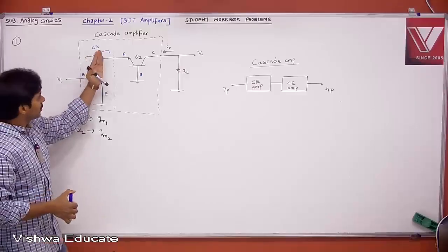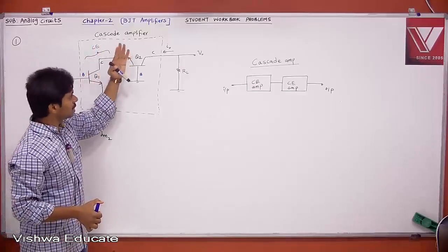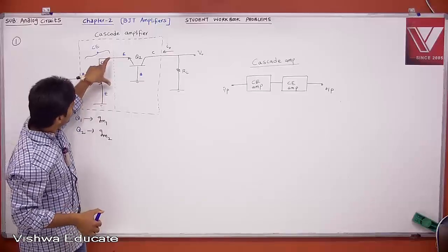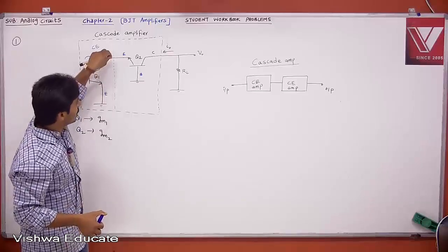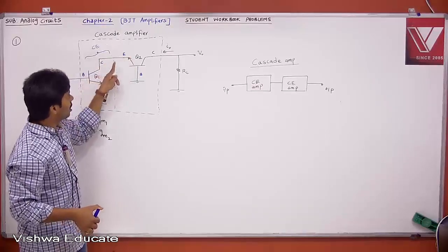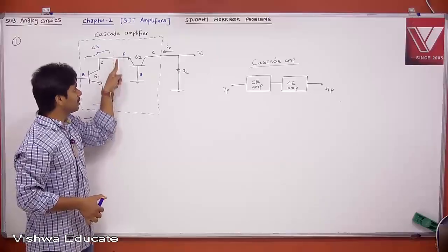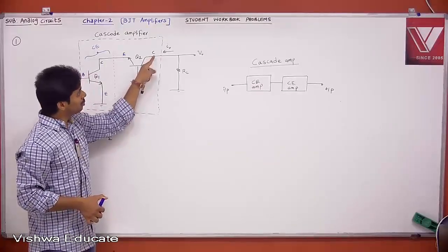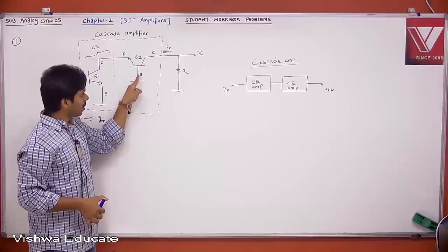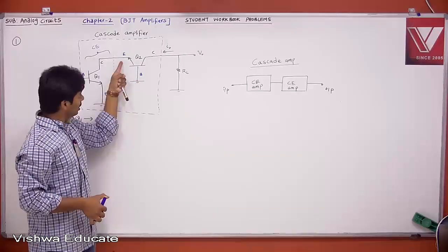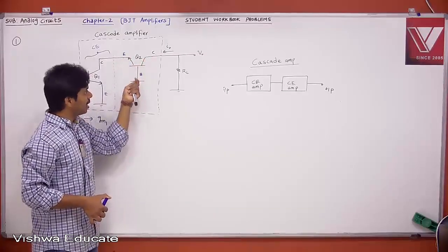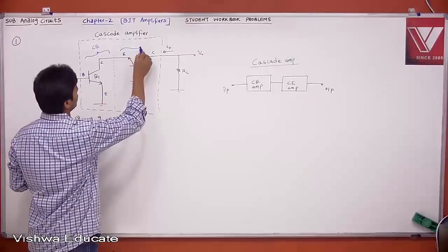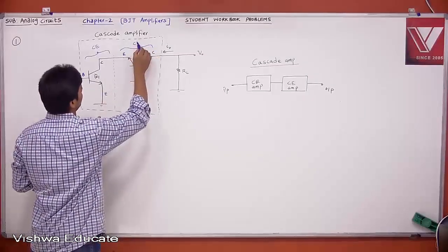Now, the output of CE you are giving to transistor 2. Let's see what this configuration is. We are applying the output of the first stage, which is the input to the second stage, at the emitter with respect to ground. Ground is nothing but your base. Taking output at the collector with respect to ground. Again, ground is nothing but your base. For both input and output of the second stage, base is common. Therefore, this configuration is your common base configuration.